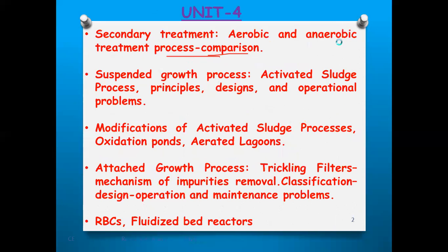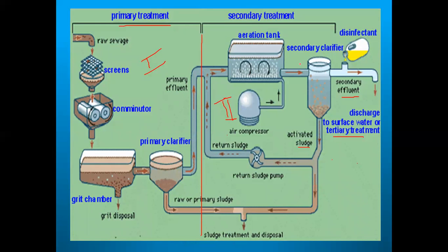See here. Whenever the secondary treatment process, water is coming from the aeration tank and in the aeration tank the aerobic and anaerobic process takes place, right? See here, the settleable materials are coming down and staying on the bottom layer. These are the trickling filters where the stones are settled. Thereby the water is treated and goes into this pipe. And in the secondary clarifier, the solid components come down, forming the activated sludge and again going into the other pipeline, the effluent water.